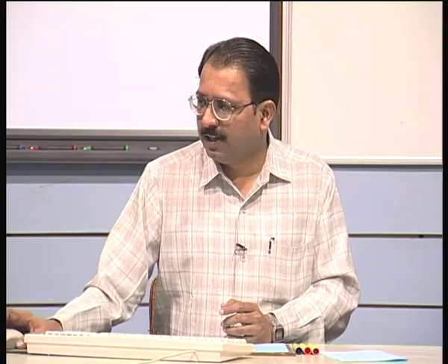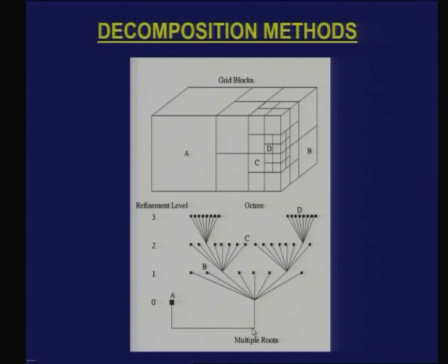So, this is basically a voxel based. Here you have the object divided into 8. In fact, what is shown here is all the cells shown as black, because it basically says that there is a material inside. But usually if there is no material, I am going to represent it as a hollow symbol, so that I can represent it as a complete tree like structure, a binary tree like structure to model a complex object.